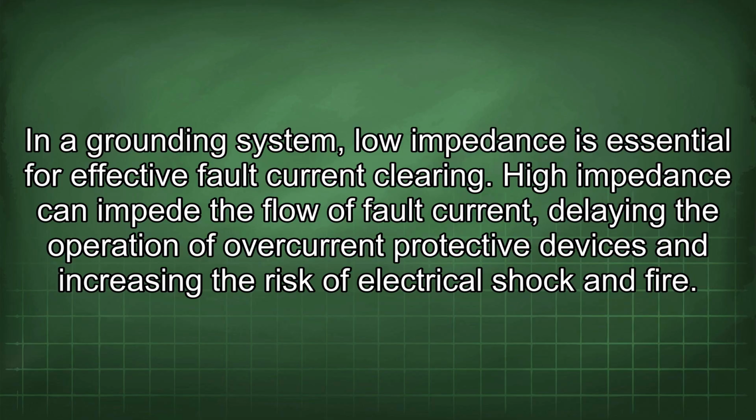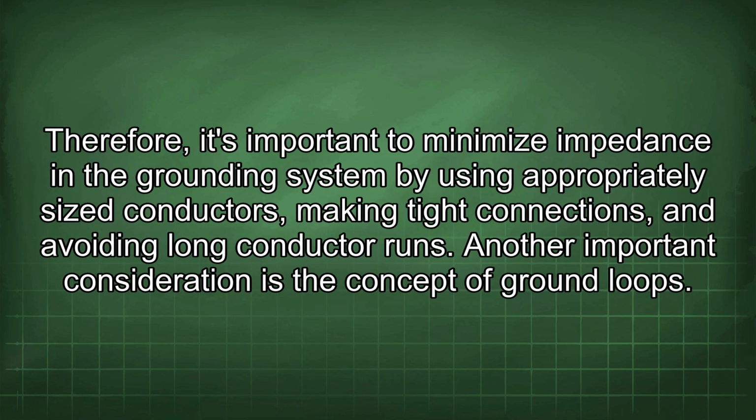High impedance can impede the flow of fault current, delaying the operation of overcurrent protective devices and increasing the risk of electrical shock and fire. Therefore, it's important to minimize impedance in the grounding system by using appropriately sized conductors, making tight connections, and avoiding long conductor runs.